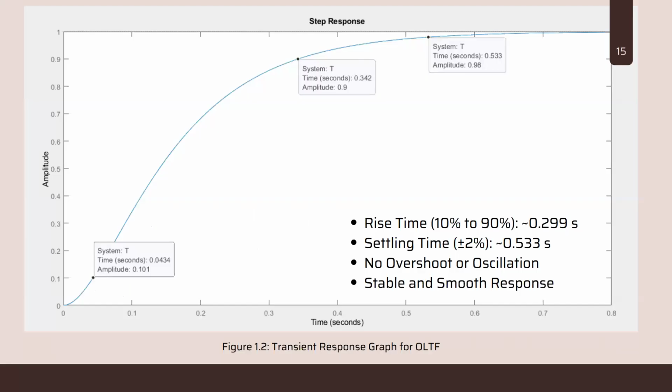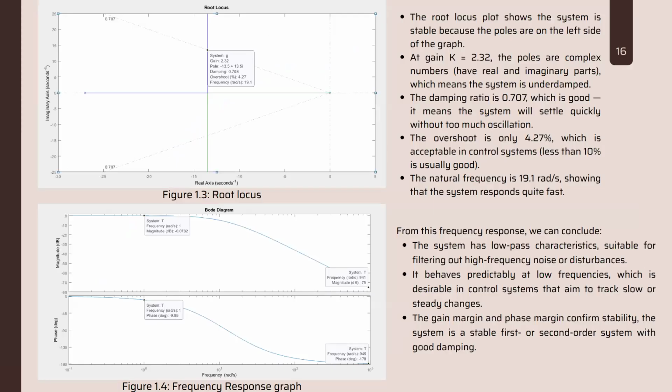So this is our step response. Our rise time is 0.299, settling time 0.523 seconds, where we have no overshoot and oscillation. The system is stable with a smooth response.